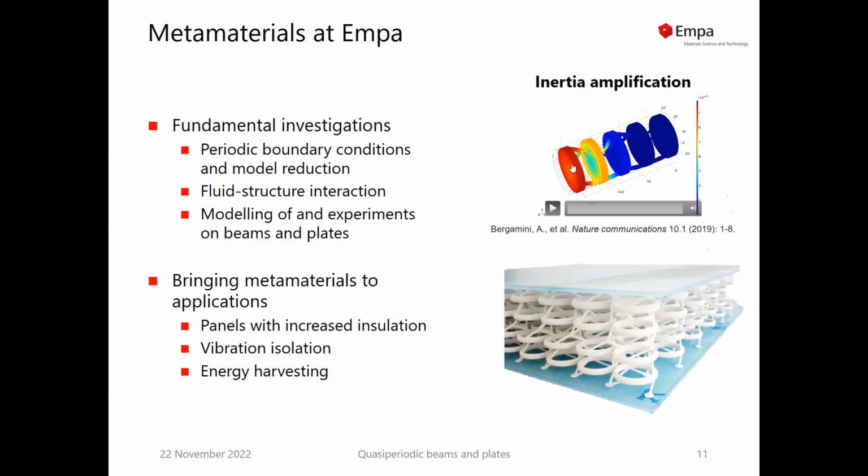So if we excite this phononic crystal from one side, we see that the energy, or the wave, is attenuated extremely fast. Within one unit cell, the amplitude of this wave is reduced by a factor 10, basically. And then using this fairly compact setup, we can decouple, for instance, 2 panes of a double leaf wall or a double window, once again with the aim to reduce the sound transmission and to increase the insulation.